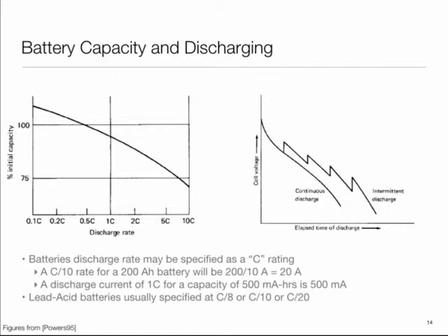But since those ions have mass, if I'm continually drawing the current, the concentration near the electrode drops. So the ions are elsewhere in the battery, but not where I want. When I stop, they get a chance to distribute evenly, and then again I can start. So that's basically what happens under the hood. It's a process of relaxation.